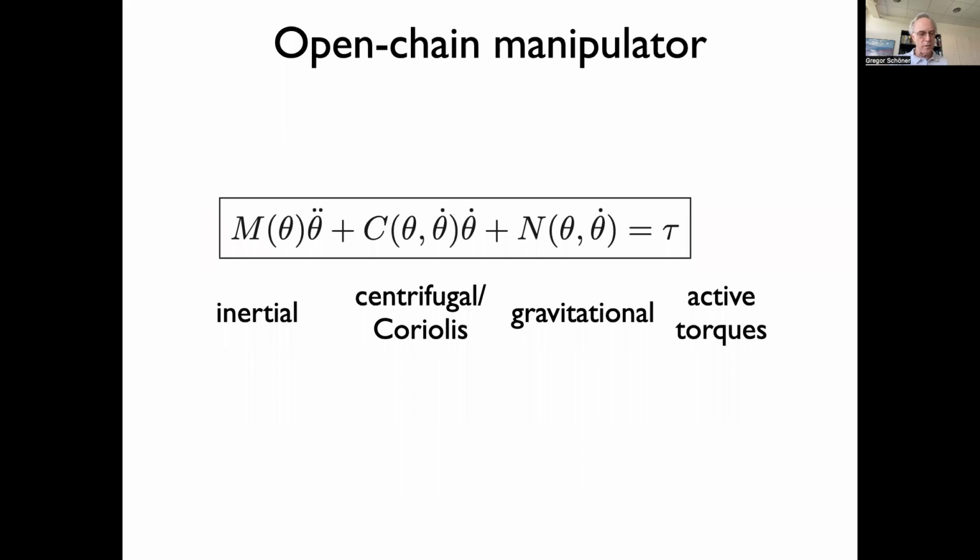approaches to that. The approach that's still being taught, I think, as the mainstream approach is called the Denavit-Hartenberg notation. In that notation, you're thinking of a kinematic chain as a sequence of reference frames, and you always have to work from the base frame.